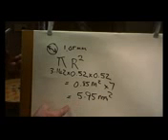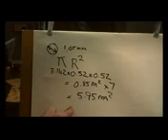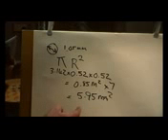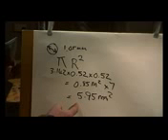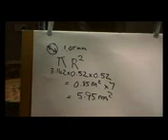Just to take this a bit further, because it's an ever expanding subject, the fatter the wire, the more current can go through it, and the lower the voltage, the more current's required for a given amount of wattage. So let's say a kilowatt at 50 volts is nominally 20 amps, but a kilowatt at 12 volts is nominally 80 amps. So the lower the voltage, the fatter the cable needs to be.